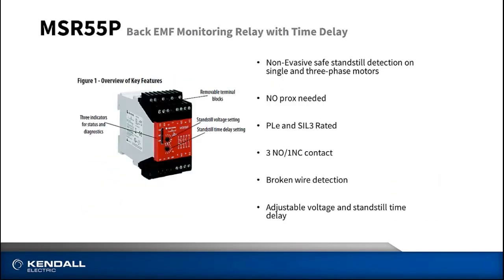The MSR55P back EMF monitor provides non-invasive safe standstill detection on single and three-phase motors. They are designed to monitor the back EMF of all electric motors that generate residual voltage while coasting to a stop, regardless of the direction of rotation. Most importantly, this is accomplished without the need for proximity sensors or an encoder. Offered in 24-volt DC, 115 and 230-volt versions, we can provide PLe and SIL 3 ratings per the installation.